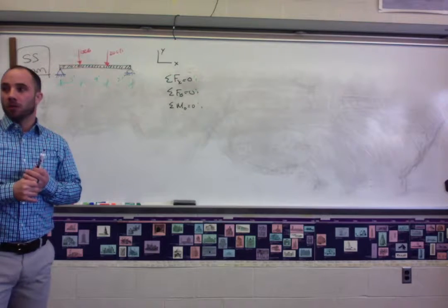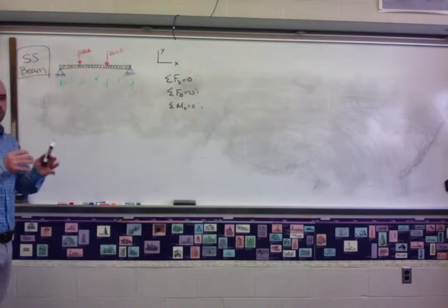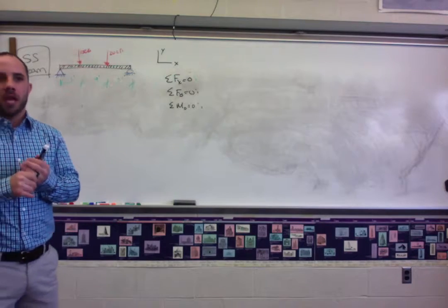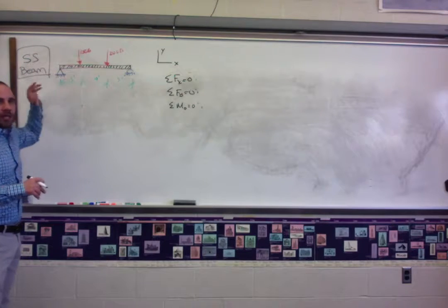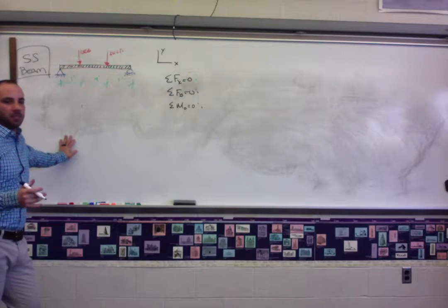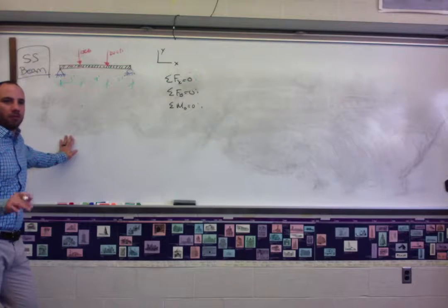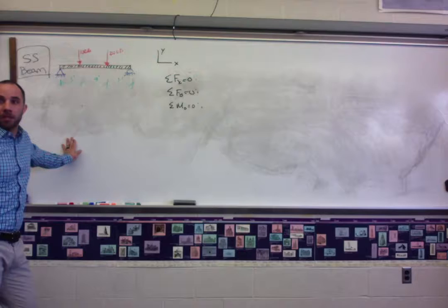If I put two rollers instead of a pin, what's going to happen? It's going to go left and right, and eventually somebody's going to crash. It needs to be stable and determinate is the engineering term. The minute this becomes a roller, it's no longer statically determinate, it's statically unstable. Okay, and there's a little formula we use, 2j equals m plus 3, to figure out if something is determinate